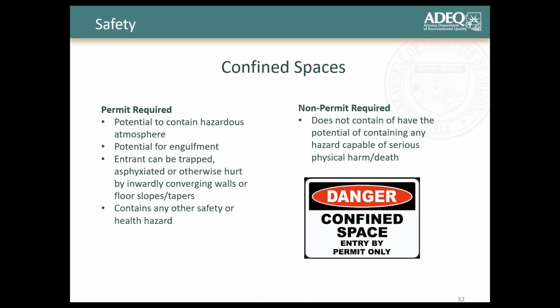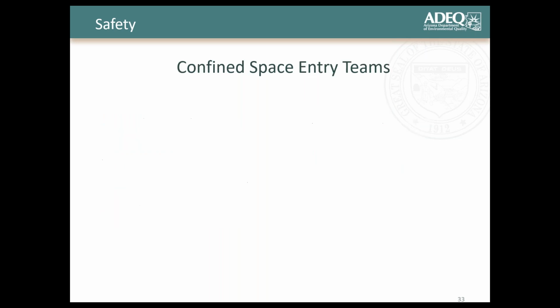space. Now, there is such a thing as a non-permit required confined space, and this is a space that does not contain any of the potential hazards that we talked about. Nonetheless, whether your agency requires a permit or has deemed a certain space non-permitted, a confined space is still a confined space, meaning that you should still have your gas detectors and your proper retrieval systems. We're talking a matter of safety, and shortly I'll share a story with you guys regarding the hazards of confined spaces.